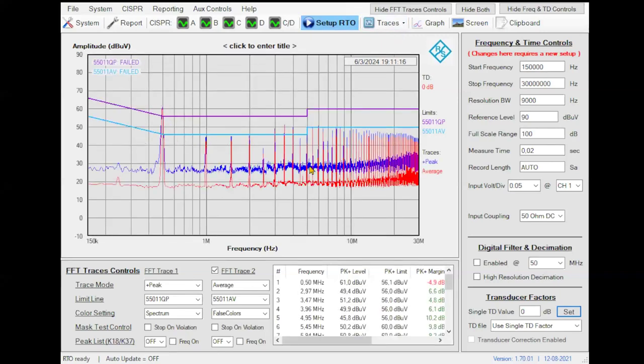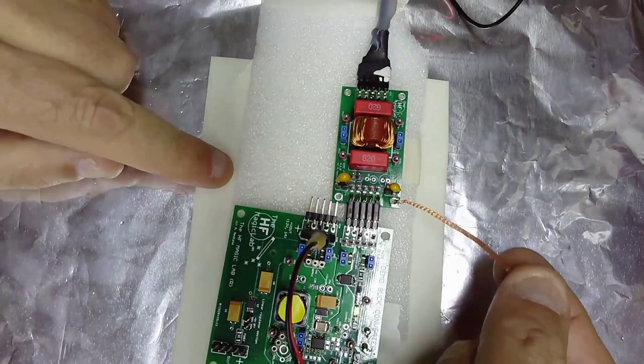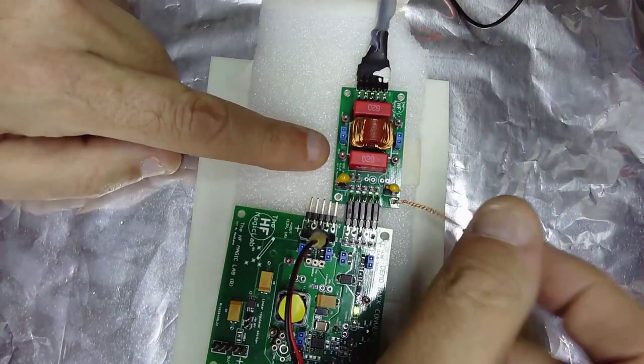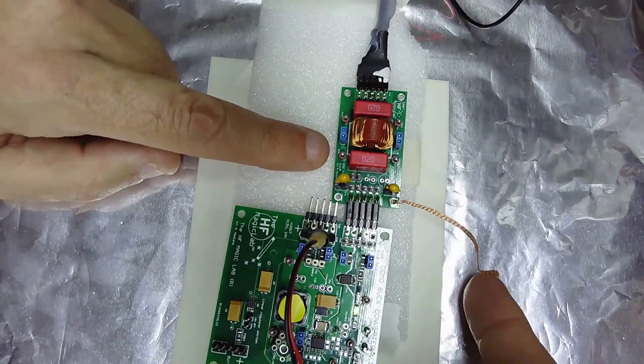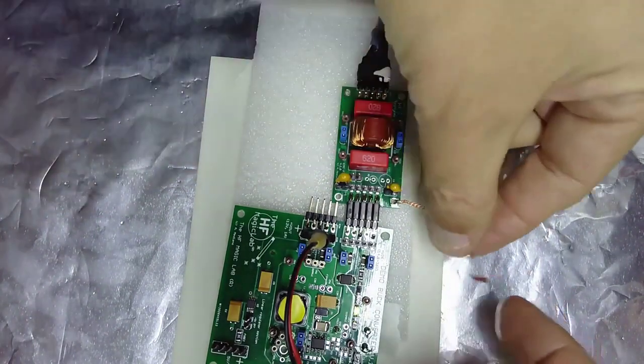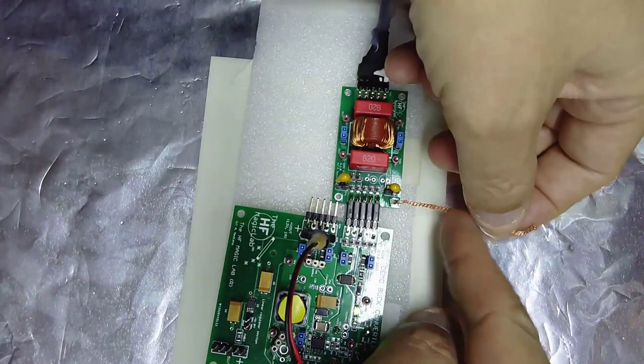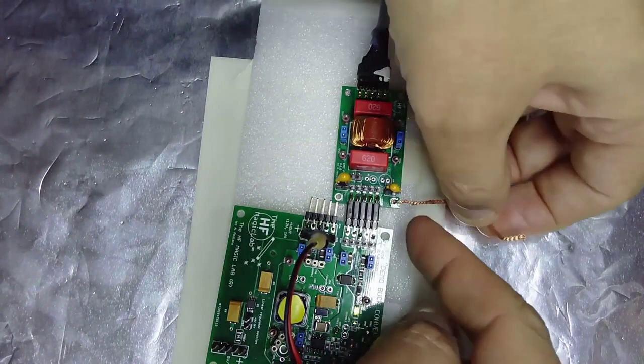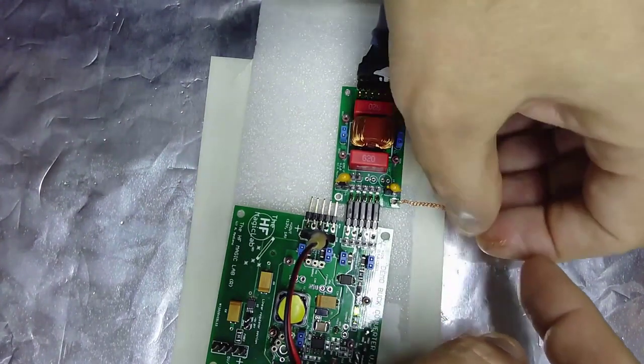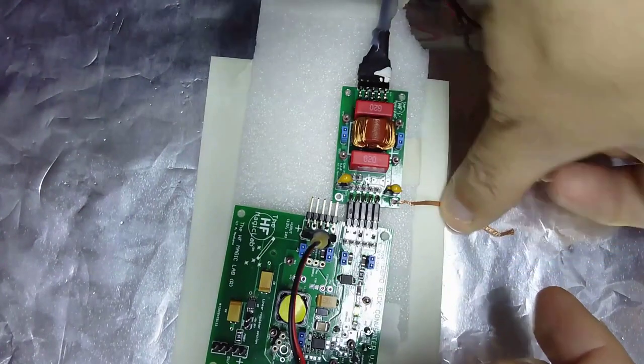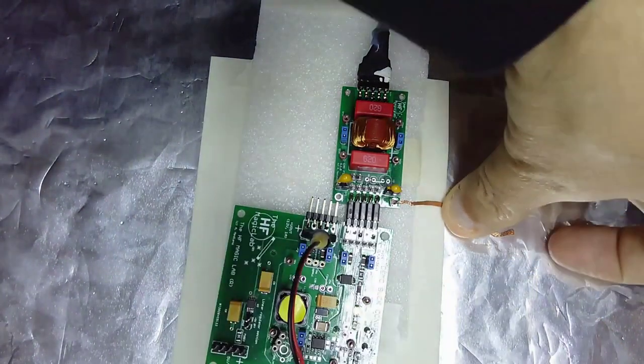Okay, and you can see that I am not fully complying. Sometimes this is due to things like this. Let's go to the cameras and see what happened. Now, the connection of the Y capacitor is not done to the metal chassis. So I have this long wire. This is not a good strategy because this is inductive, but for the demo it will work. What you are going to see is how I connect the Y capacitors directly with my finger to the chassis.